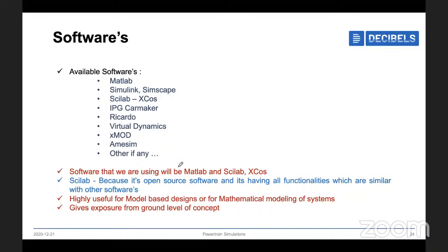If you're not good at coding, and if you know mathematical equations, then you can go with Simulink and Simscape implementation. But I would always suggest Simulink because it will give you model based design, and it will give a clearer idea of how a particular component is working, like how the gear ratio or the motor is working. You can derive the equations and use those equations.